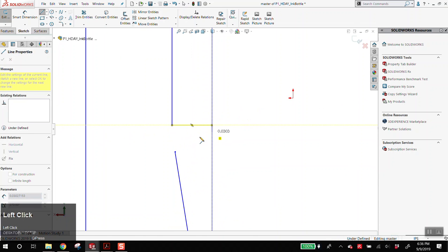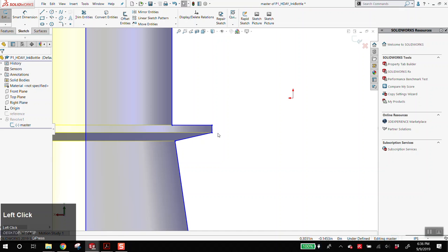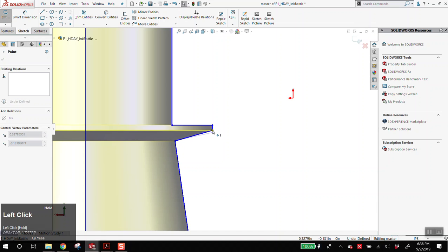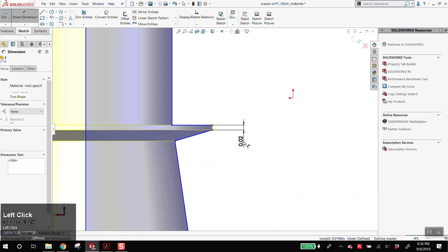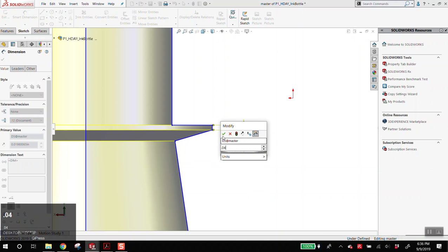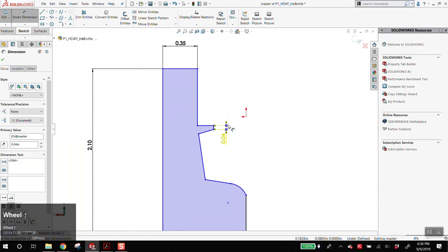This is how I would do this, just like that. Something like that. If you want, you can get the calipers and measure. That's probably not necessary. Again, when in doubt, it's probably a millimeter. So 0.04 is probably what this is. The reason for that is anything smaller than a millimeter is probably not easy to mold.